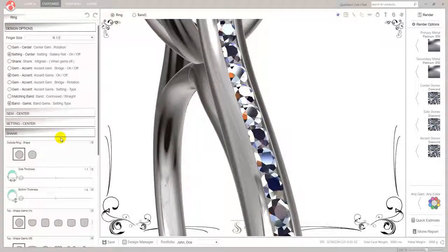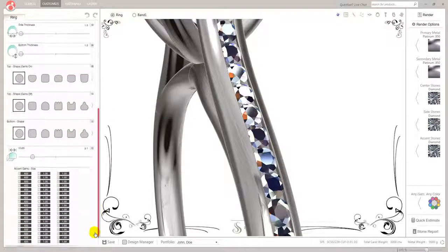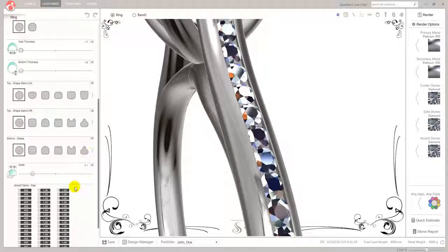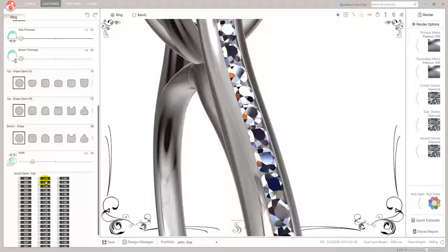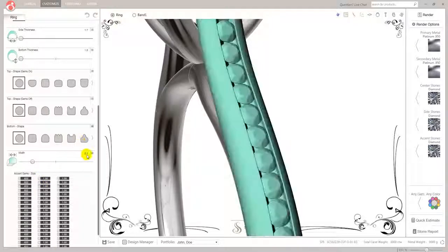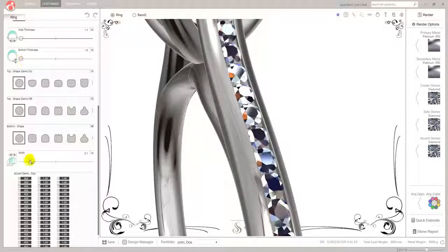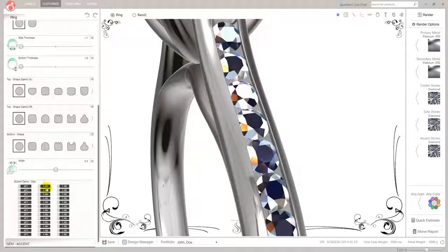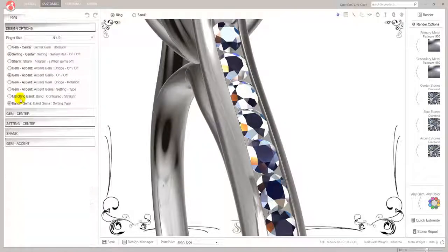Let's see what size those stones are, because everything works in relation to what sizes you've picked. So it's saying a 2.1mm stone. Oh no, sorry, it's saying 1mm stones because you've got a 2.1mm. Still has got your back on this, that you can't make sillies, and if you do make a silly, they'll correct it for you. So if I increase the width of the shank, so let's say I took that up to 2.5mm, watch what happens with the stones. The stones have gone up to 1.5mm. So this has a, let's just turn that off again.